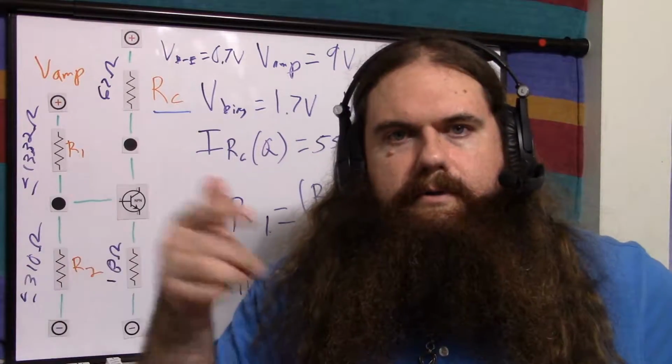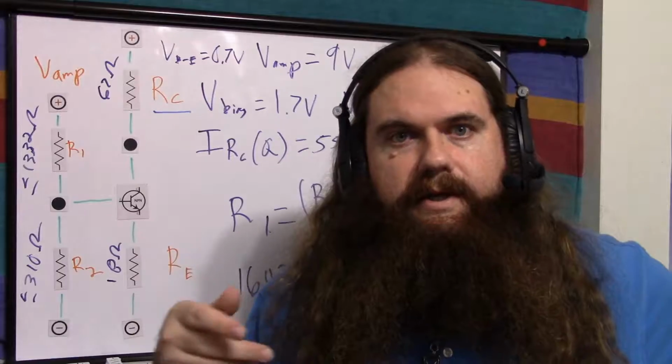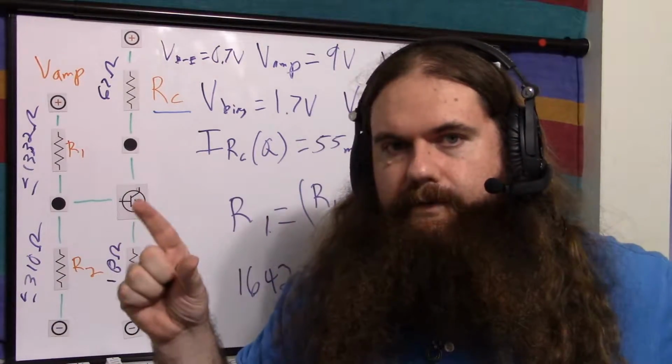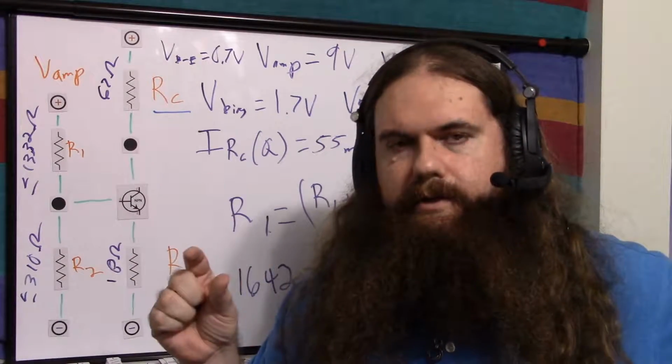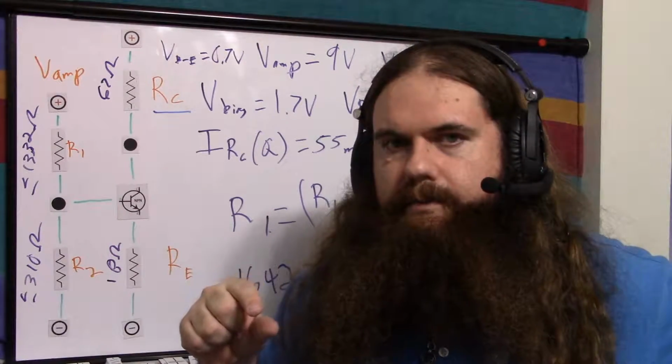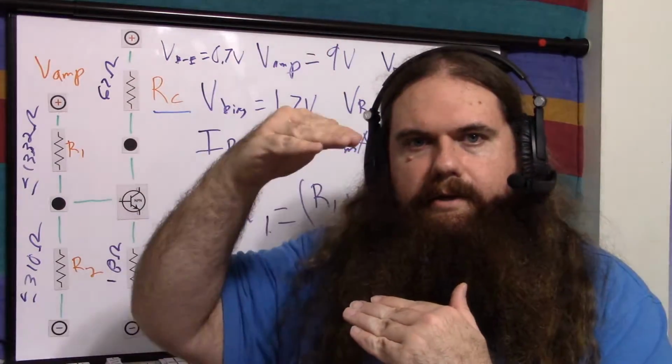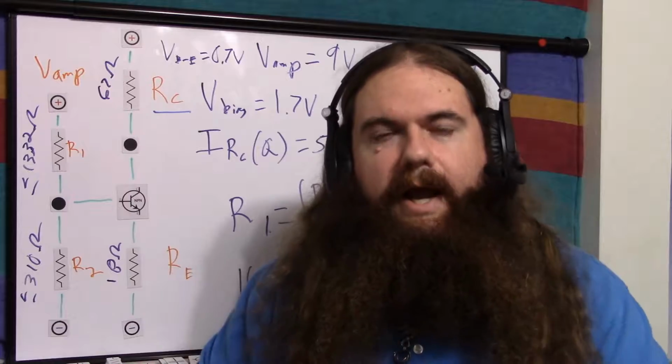It follows more along the lines of a BJT being modeled as a current-controlled device. So we're more directly saying we get a voltage on the collector based on the current through the collector, based on the current to the base. So I just think it makes more sense that way. You know that little bar chart I made? It's more in line with what we're actually doing.